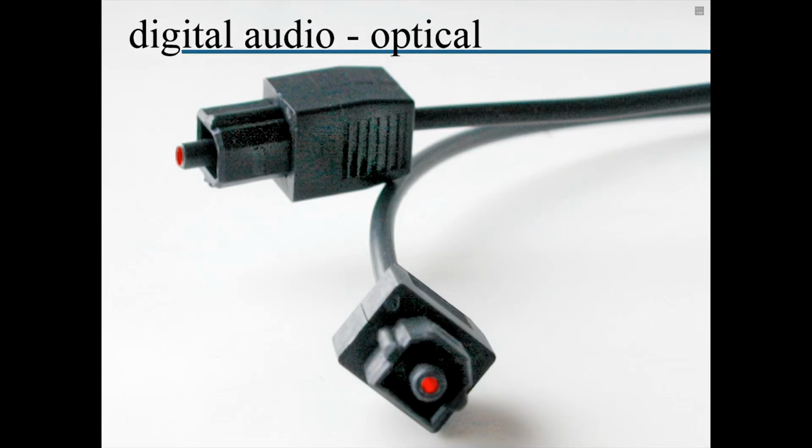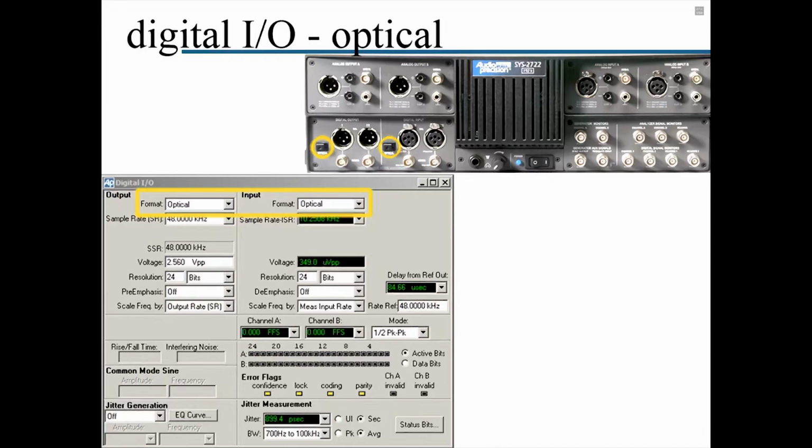The optical connection is via Toslink optical fiber, a standard introduced by Toshiba. When using Toslink in audio precision instruments, connect to the optical connectors in the digital I/O. Select the optical output and input format in the digital I/O panel.